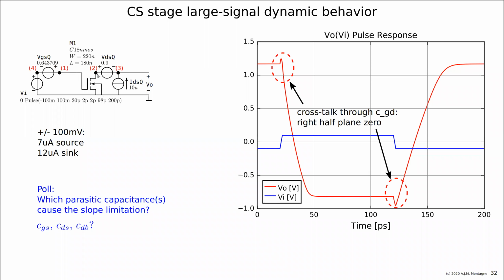The voltage on these two capacitors changes at node 2. So the voltage there is changing and it needs current. And that current is delivered either by the bias voltage source at the output, or by the current source, but it takes time. And you see here we are discharging with the sink current of the device, and here we are charging with the 10 microamps.